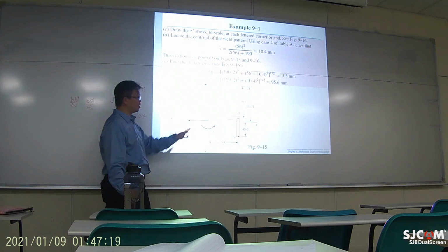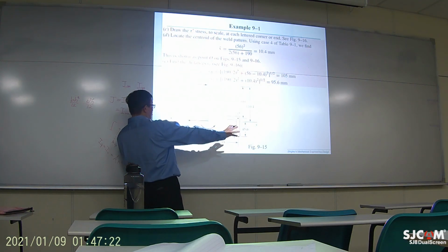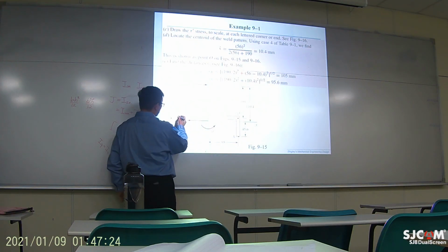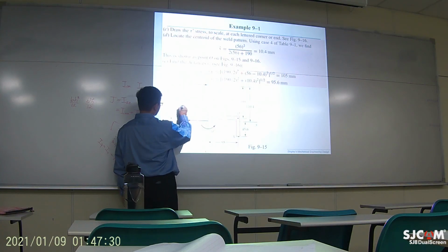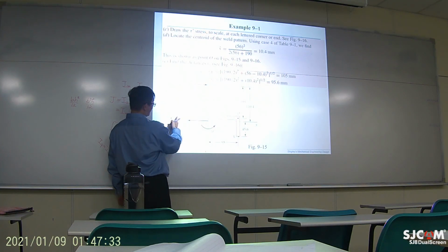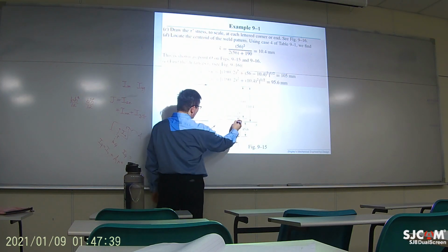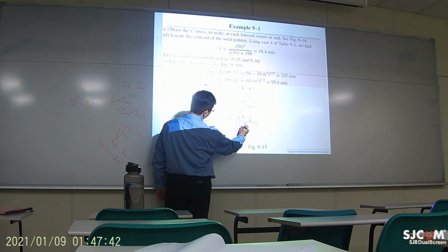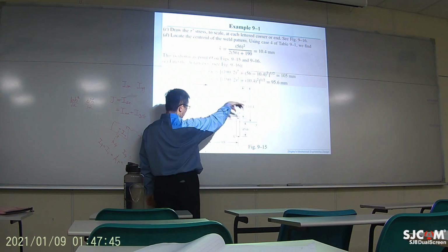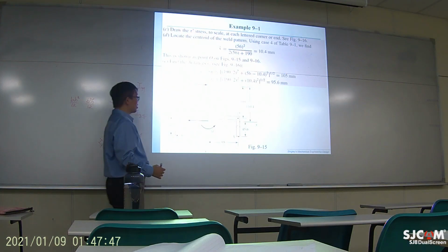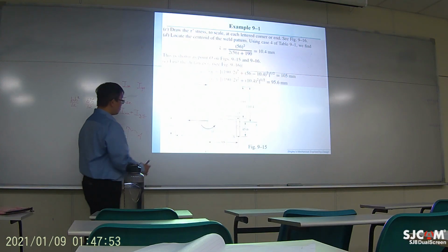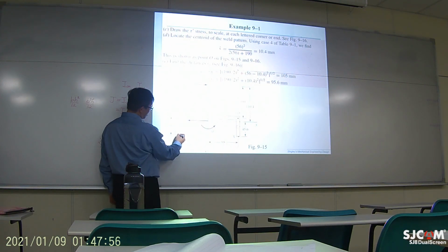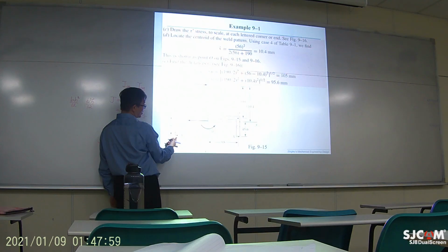They're treating A, B, and CD separately. How come? It's symmetrical from left and right. So the radius right here is the same, and the shear, the tau double prime for C point will be going this way, and then for the shear going, it will be clockwise. So the tau double prime will be going that way, and they have the same magnitude because they have the same radius. But for B, it has a wider radius.